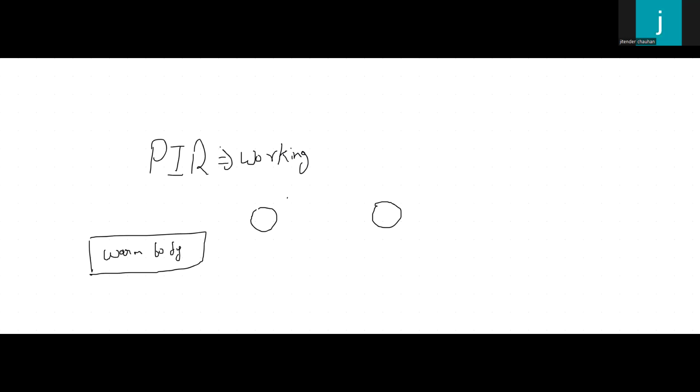Before that, the sensor was in an idle condition, no movement, the same IR radiation it gets from that environment. But when a human or animal body, which has heat inside it, enters the sensor's field of view, it disrupts that balance. How? The moving object causes a change in the amount of infrared radiation detected by one slot relative to the other slot.